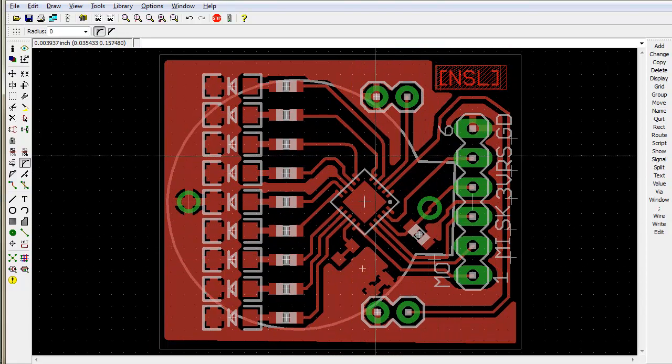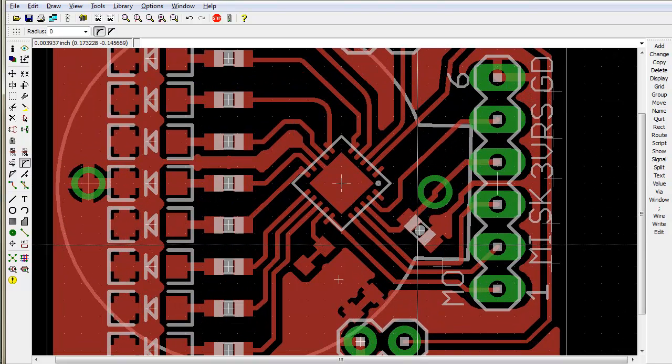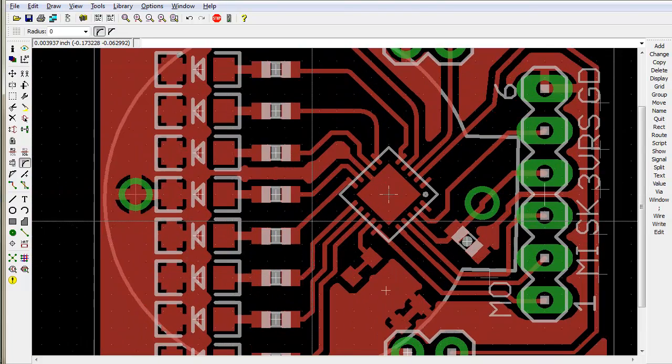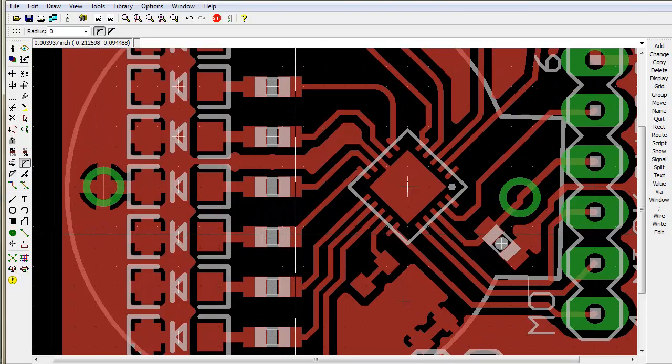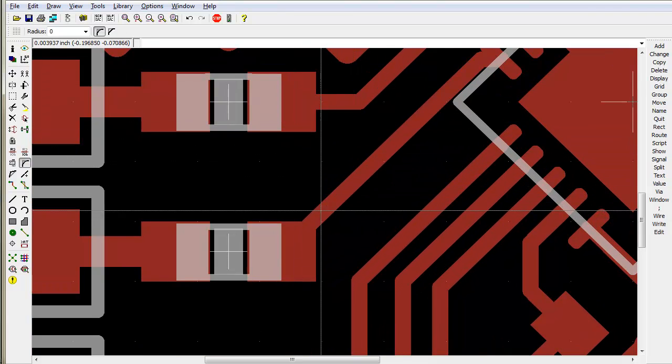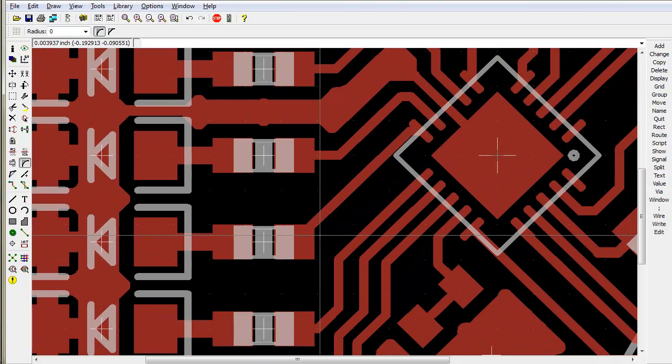Traces like right angles and stuff like that people talk about, but for this kind of level of work you're never going to care about it, and there's a lot of debate on whether right angles really do anything in PCB design anyway. The diagonal stuff like this one tends to be a little bit hard just because of the milling process. Think about the milling bit coming down here and turning. There's a lot more chances for it to actually be damaged, so